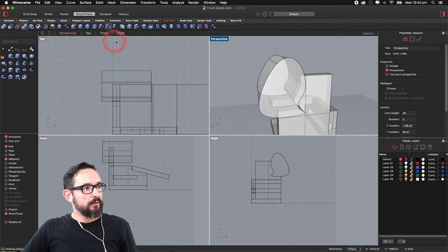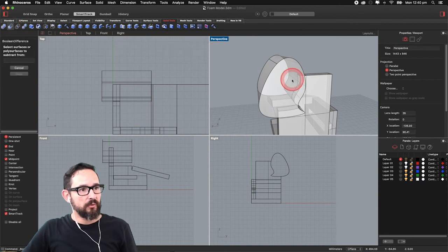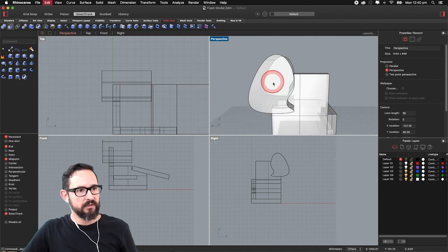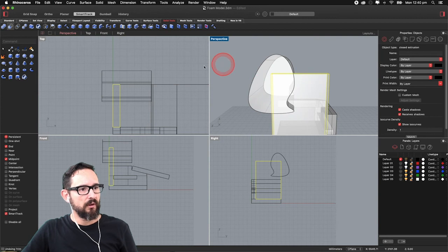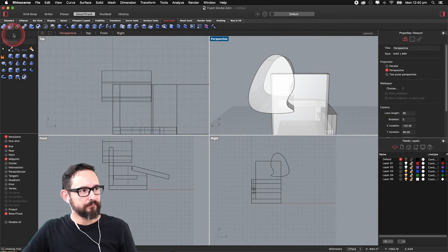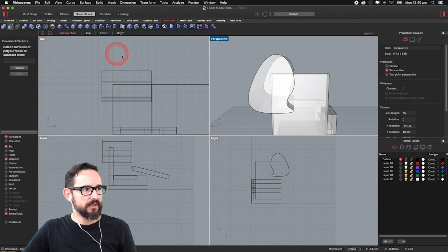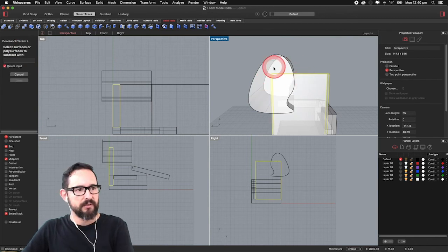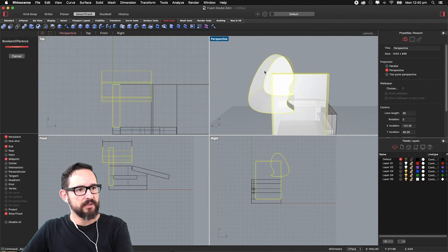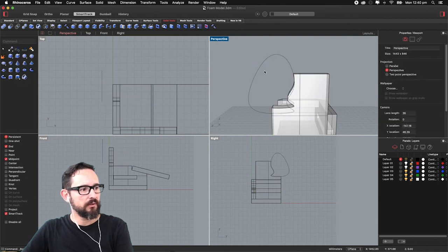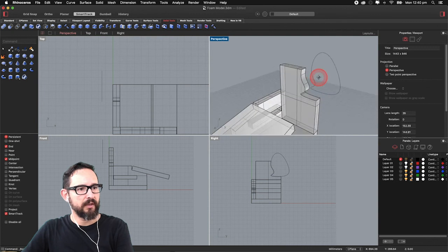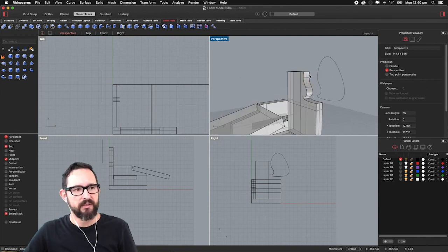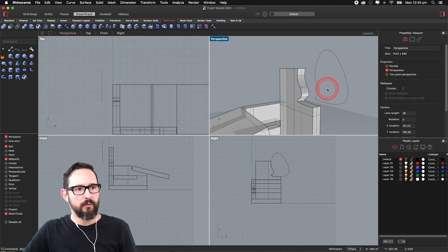So Boolean, and select Boolean surfaces. Oh, sorry, I need to go back. I still have it cut, I didn't undo. Okay, so if you go to the Boolean, it will ask you to select the surface to subtract from, this one, and subtract with this one. Press enter. Let's see if it is going to do it. Yep, and that did work. So the trim didn't, this one does. It allows you to do the same kind of operations.